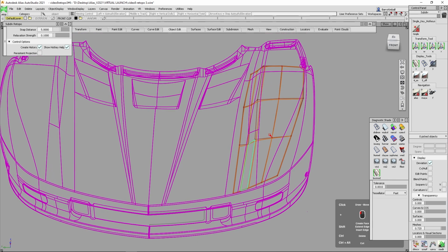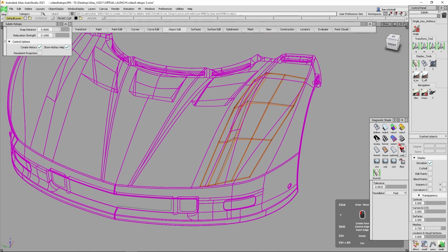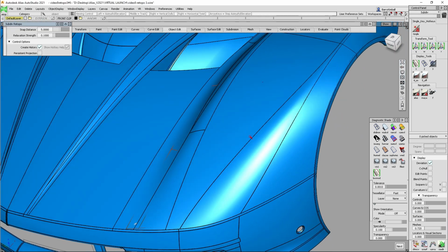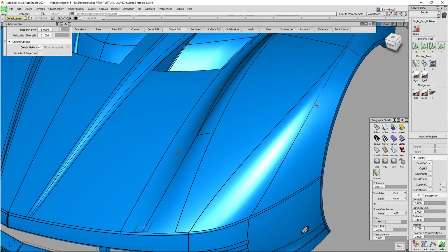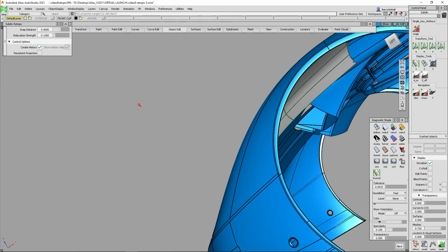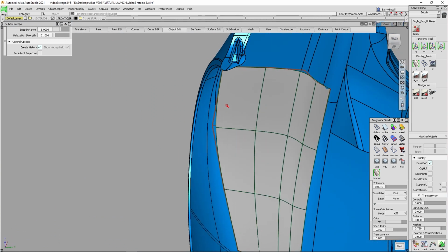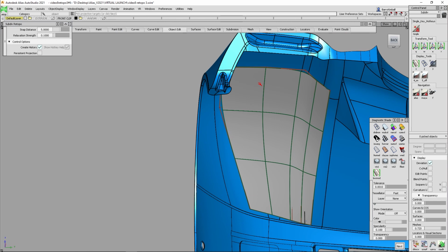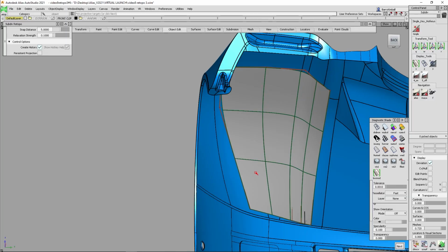So we got a couple of kinds of reference data that we can use. We can turn on some shading here and see if we can see a quick difference. If you look, you can see the vertices poking through. All of the vertices are sitting right on that scan data. The limit surfaces are below, but you're going to find that if you build a nice topology where your control cage follows the surface flow, you'll get a pretty close match, and sometimes you can just scale it up just a little bit to get it to better match your surface data.